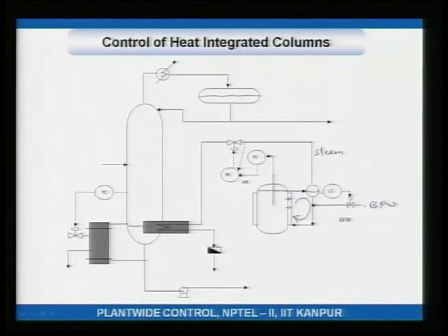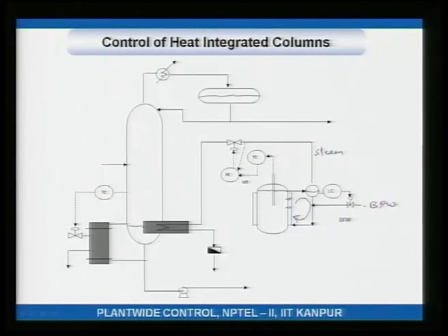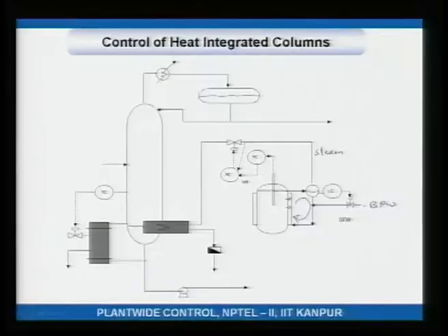Of course, this reboil is not enough to get the kind of split that I want. So, let us say the amount of reboiler duty that I want is X, and the steam from the reactor is giving me maybe 70% or 60% of the total reboiler duty that I want. The remainder 30-40% is coming from this trim reboiler. This is called a trim reboiler.